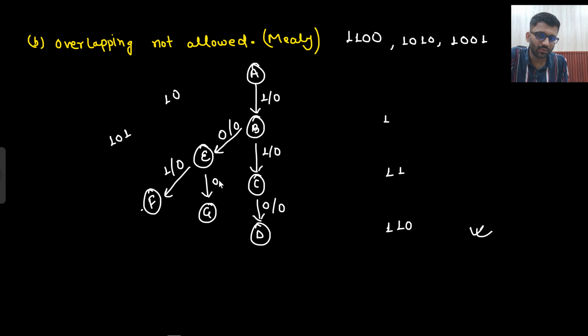If applied input is 0, here at G I am already having 1 0 0. If 1 is applied, the sequence is detected. If 0 is applied, then something else will happen. But certainly I do not require any other stage. That's for sure. So for that, I know that I only require till stage G. So here I can get to know that I require 7 states: 1, 2, 3, 4, 5, 6, 7. In case of 7 states, I will be able to make it.